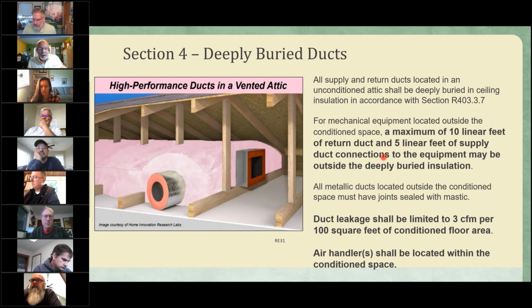Yeah, so the air handler has to be in conditioned space. If you're taking any points out of section 4, the air handler has to be in conditioned space. You can have some return air, some supply ducts outside of conditioned space, but it's real minimal. So keep that in mind if you're taking deeply buried ducts, that the air handler also has to be in